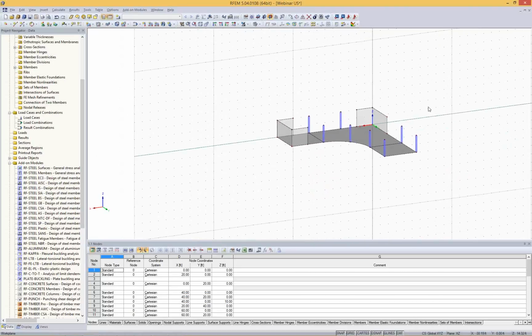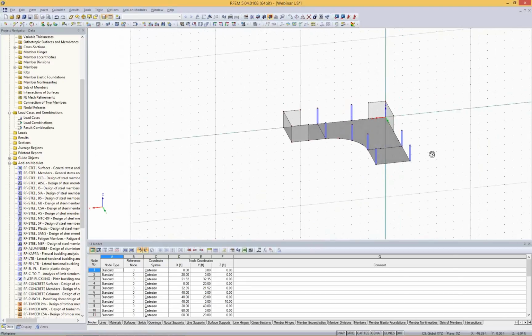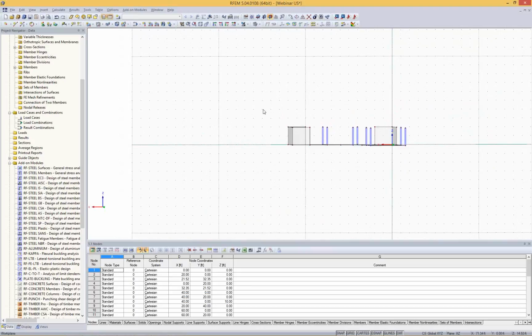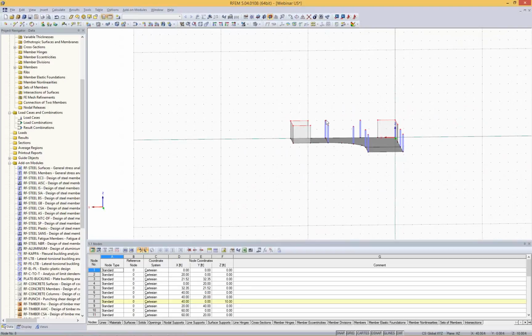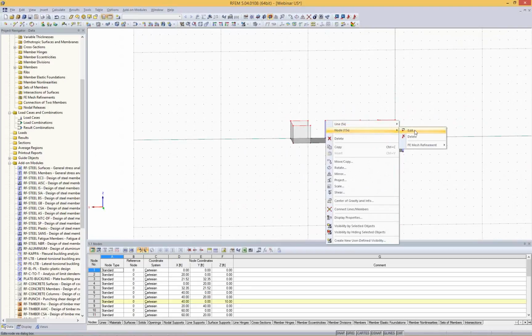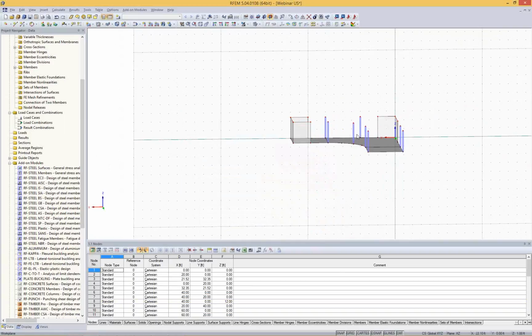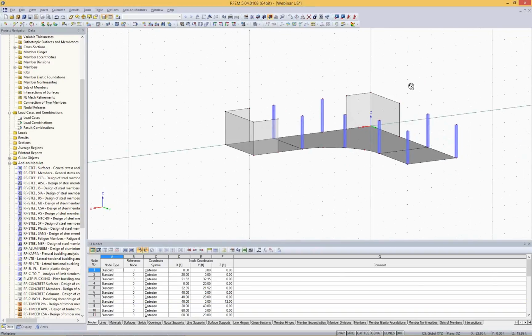So that's pretty much it for the first floor. And now we want to prepare the ceiling slab and the other storey. So at first I want to change, for example, the height of my floors, and I could easily do that by selecting all these nodes and editing them, and you will see there's a value over there for the height, and I want to modify this one as 12 feet in height, and it changes this height automatically.